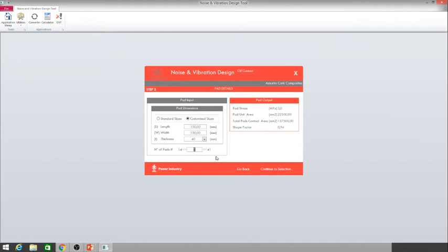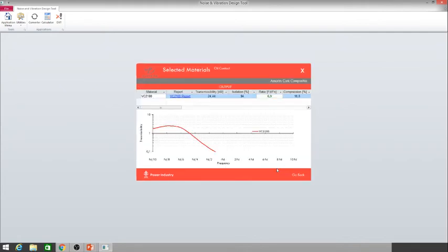So instead of 14, we are going to use 21, multiples of 7. Meaning in each leg we're going to have 3 square pads of 150 millimeters. If we continue, we have again the solution, and you see with similar isolation, 93 was the first case, in this case 94% in isolation. So again, both solutions can be used.